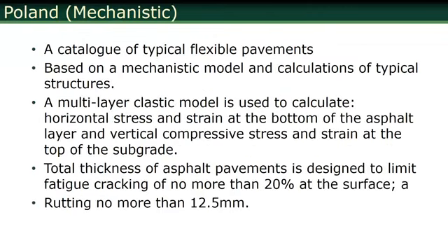So it's more empirical. Poland is mechanistic, interestingly, a catalog of also flexible pavements. They have flexible pavements, but this catalog is developed based on a mechanistic model and calculations of typical structures in that area. And they also use a multi-layered elastic model.